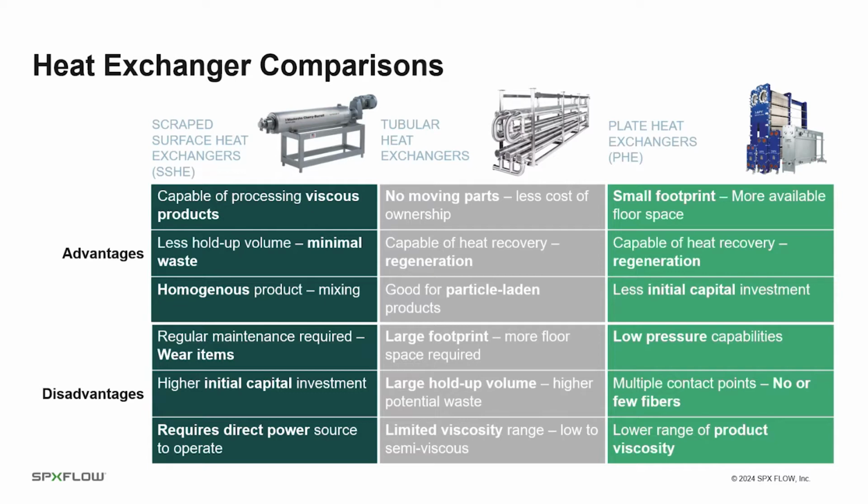First, the advantages of a plate heat exchanger are a small footprint. A lot of space in plants is very valuable. So the plate heat exchanger, just by its design, will take up less floor space than your typical other types of heat exchangers. It also provides a great opportunity for heat transfer. And what I mean there is regeneration, heat recovery, which is very important for some of the ROI calculations for these customers. And it's a low additional cost of investment.